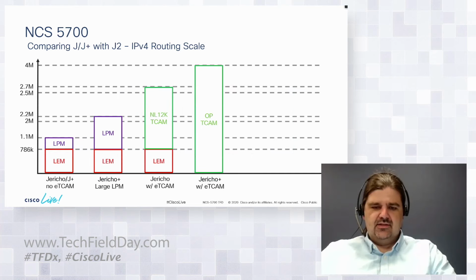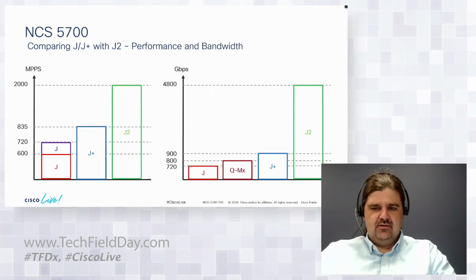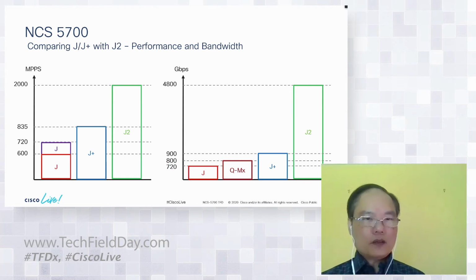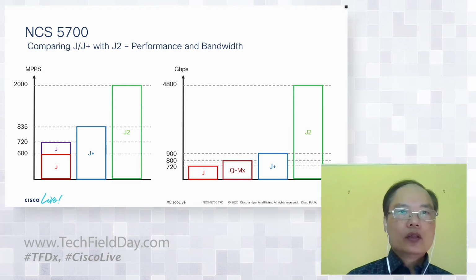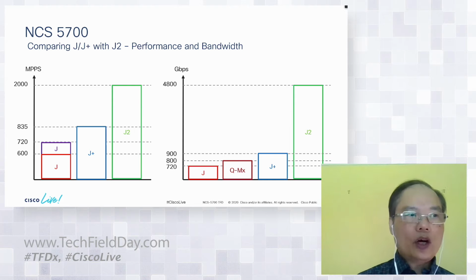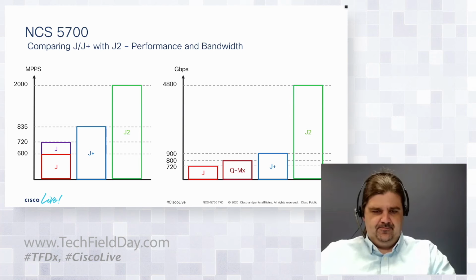So I think you're implying there that the size of the packet doesn't really matter. The size of the packet, because the average packet size on the internet is increasing, so for a forwarding chip, it's better to optimize it for larger line rate packet sizes in order to fully utilize the bandwidth available on the chipset. Okay, thank you.